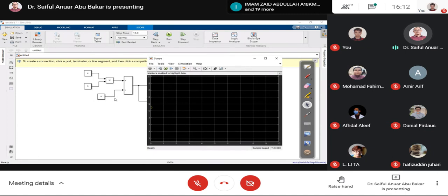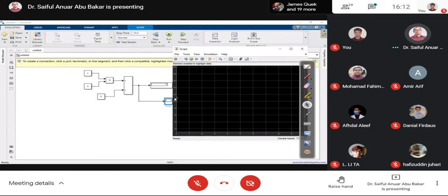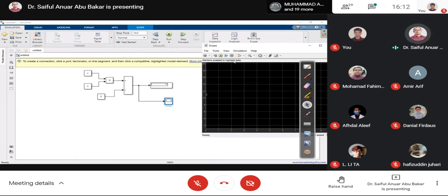Okay, for all the versions, when you run a constant value, usually you're going to get a straight line at the value of 11 from the start of the simulation time till the end. But in this case, this version, I think just installed 2020, just stopped at this value, showing that this result is preferably viewed using the display block, not the scope.